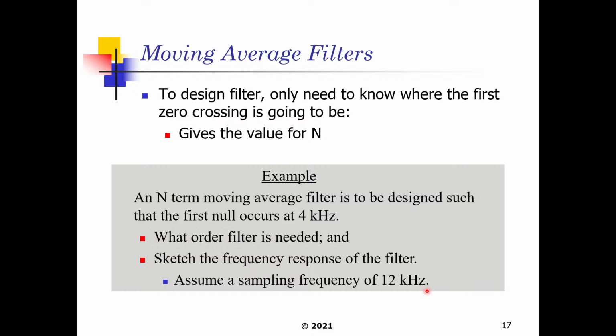If there are no spikes in the signal and you apply the moving average filter, you're just wasting your time, because it doesn't eliminate any high frequency information that does not exist in the signal to begin with. So like I said, it's only good if you have high frequency information that's corrupting your signal. Whereas if you just have low frequency information within the entire signal, a moving average filter is basically worthless. So yes, it does maintain the shape. The only thing that it will eliminate from the signal is any particular noise spikes, be they positive or negative in nature.